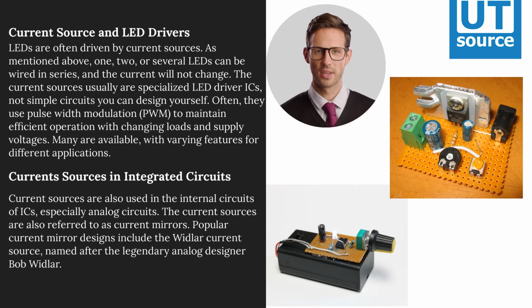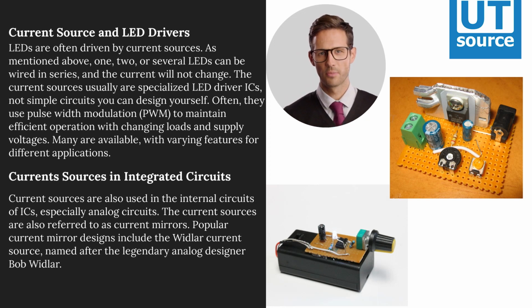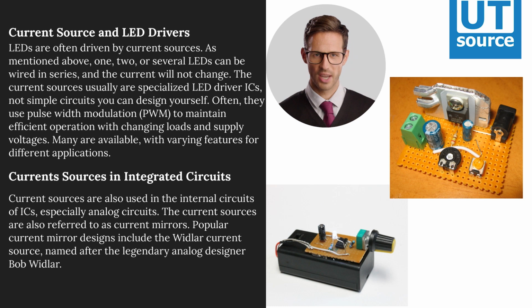Current source and LED drivers. LEDs are often driven by current sources. As mentioned above, 1, 2, or several LEDs can be wired in series, and the current will not change. The current sources usually are specialized LED driver ICs, not simple circuits you can design yourself. Often they use pulse width modulation, PWM, to maintain efficient operation with changing loads and supply voltages. Many are available with varying features for different applications. To learn a bit more, here are links to a simple IC from Diodes Incorporated and one from onsemi.